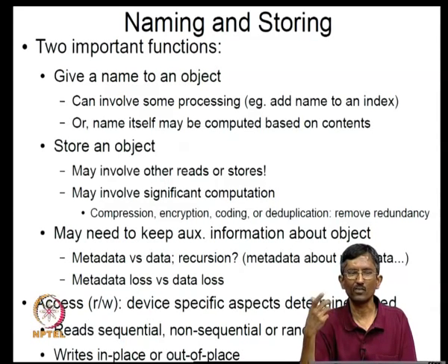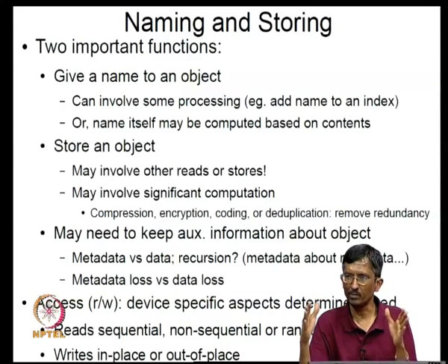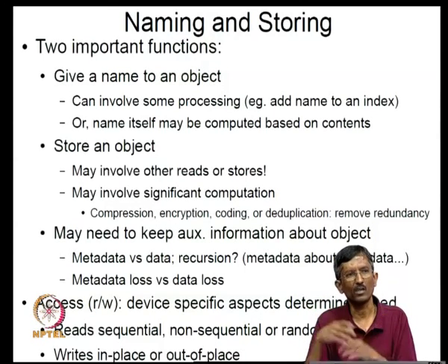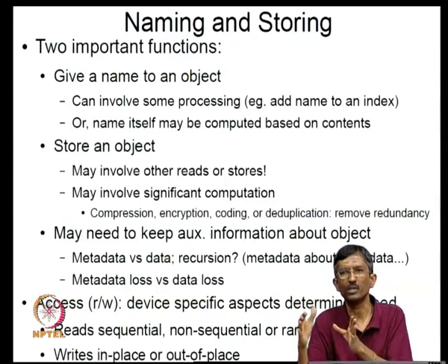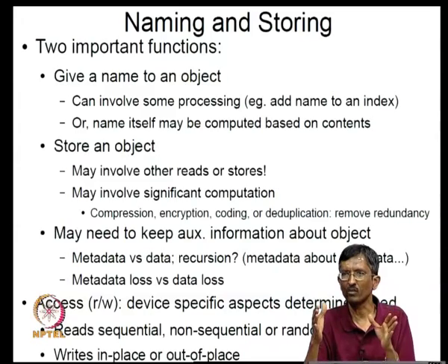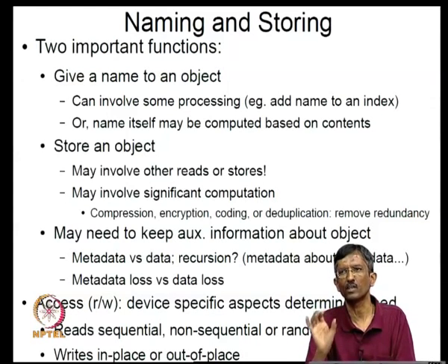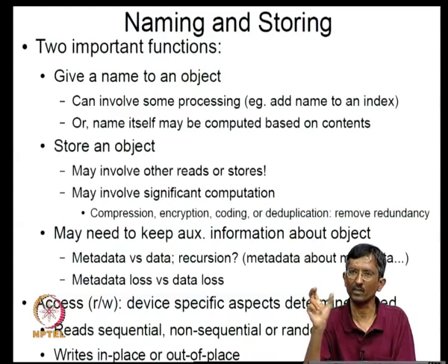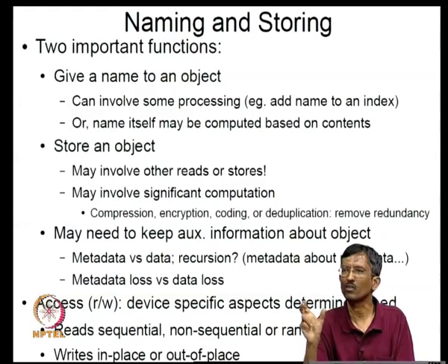For example, in disks they use something called Reed-Solomon coding widely, and for every 512 bits, as much as about 40 to 50 or 60 bits are used to encode that 512 bits, so that even if a burst of errors takes place, for example 4 or 5 bits get lost or even 10 bits get lost, I can still recover the whole thing.